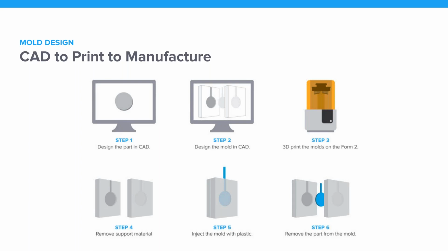You want to be careful when you're using a 3D printed mold. High pressure and high clamping forces can and will probably break the mold, so you want to reduce those. You can, of course, sand and polish the parts if you want. 3D printed molds are especially good for thermosets.